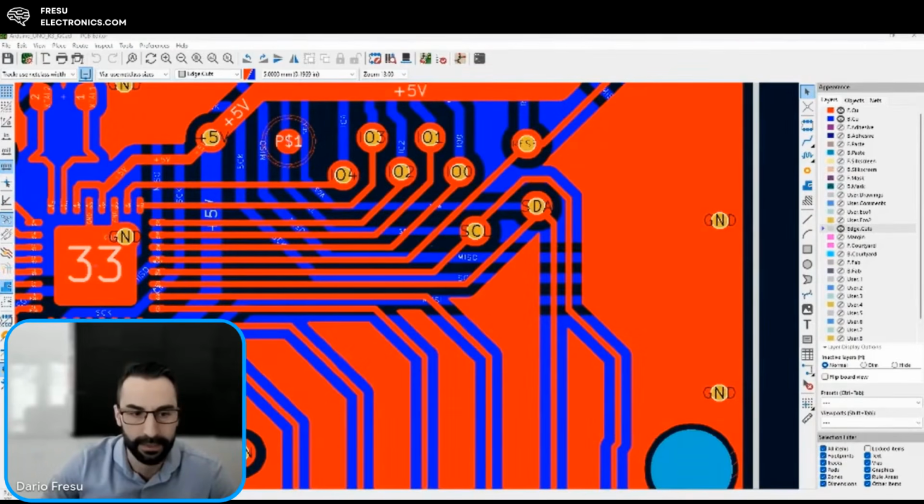When the signal is trying to propagate from this trace in here, it's not going to go like this and then go through the vias, spread, and reach a point that it has to reach. Because it is not going to propagate in terms of electrons, but in terms of fields. So how can the field be established in here? We're going to see that when we analyze it under the software. The fields are going to be established between these two copper traces. This is already crosstalk. Also between these copper traces.